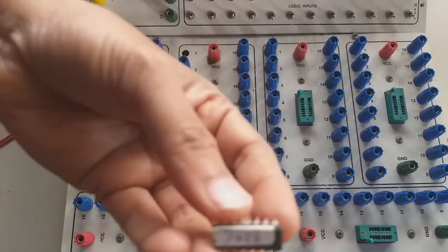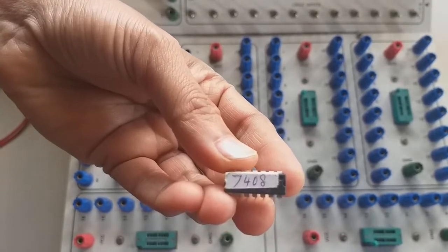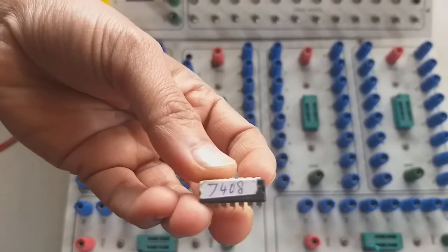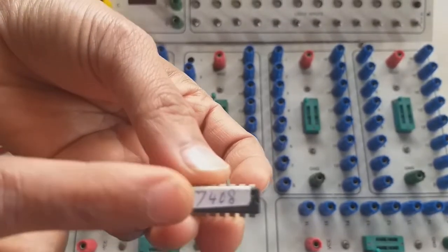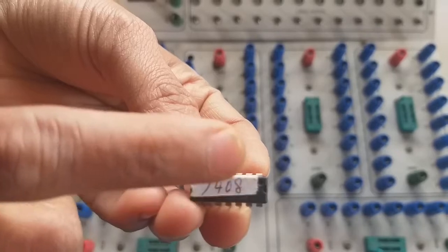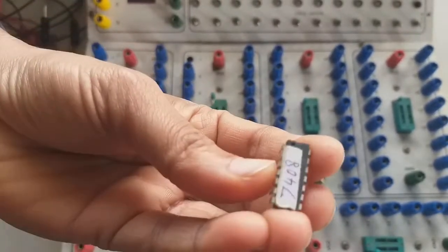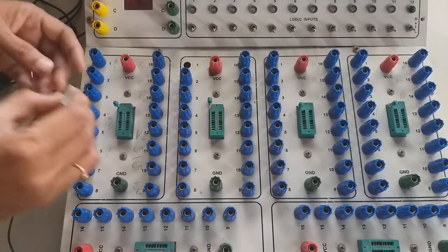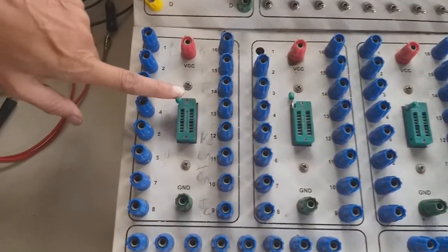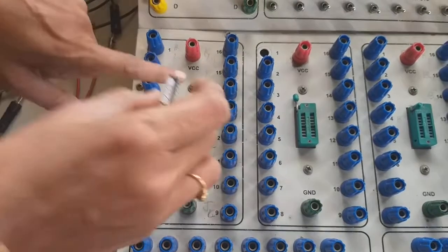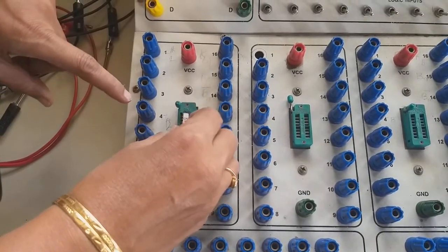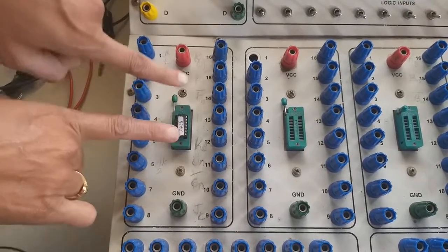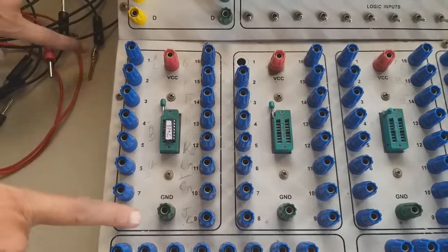Okay, the next basic gate is 7408, that is the AND gate. So we are going to realize how the AND gate works. Practically we will see how the AND gate works. As you can see, you have a notch over here. This should be placed towards the north side. In the sense, you should plug it in, fit in this fashion to the slot. So see that the notch is facing upwards. Then place the IC inside the socket, gently press it, then press the notch towards the north side. This fixes the IC into this slot.